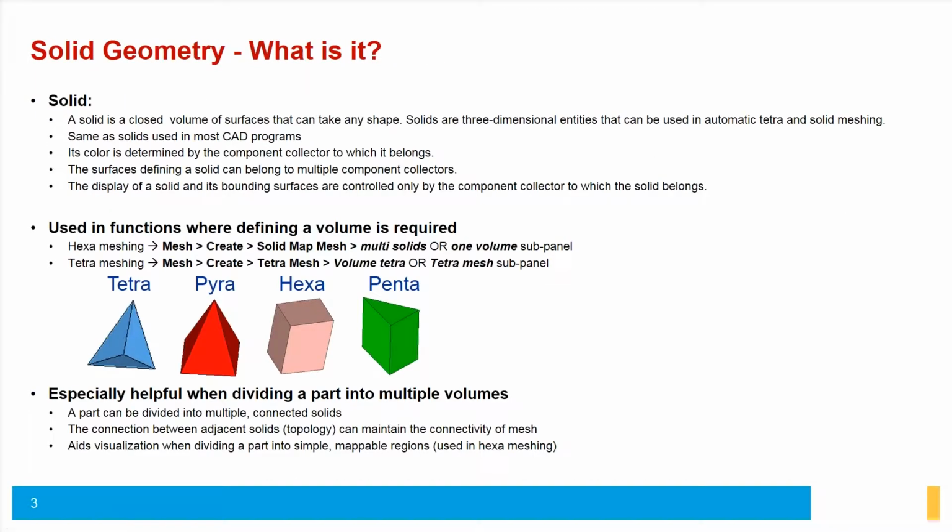Okay, so when we're talking about 3D meshing, we are talking about these 3D elements. These are the four main types of elements that we're going to be working with, and these are really the only types of elements you'll see going around. While we had the quad elements, which had 4 nodes, one on each point, so we had some quad 4 elements, and we also had triads, which had tria 3s, where they have 1 node on each point. And now we have hexa elements, which are these cube hexahedral elements. Then we have these penta elements, pyra, and tetra.